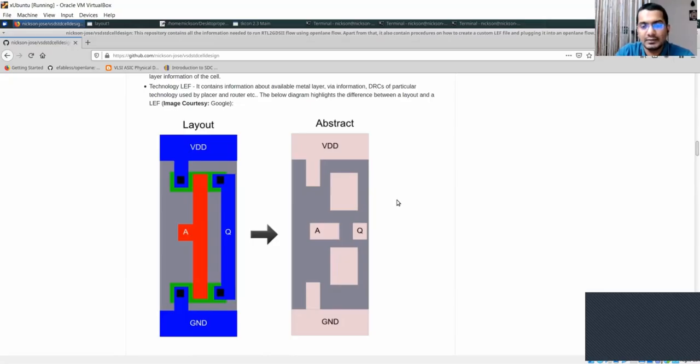It acts as an adhesion layer for the SiO2 and also acts as a barrier between the lower metal layers and the higher metal layers. And the next step is to again deposit tungsten. That's the same thing that we did over here and over here. It's basically now we are making the contact holes. So the steps again, from the bottom till the top, remain the same.